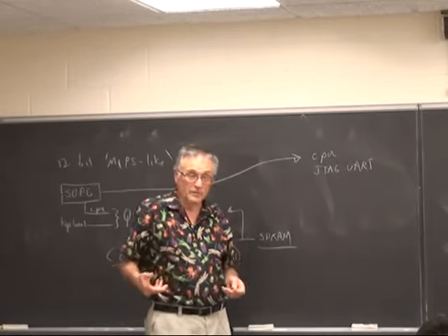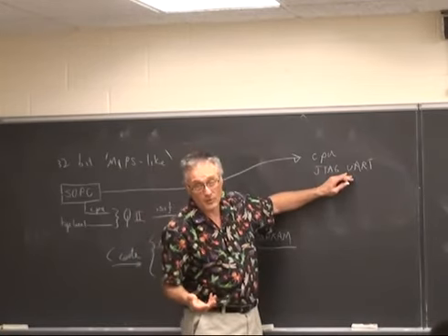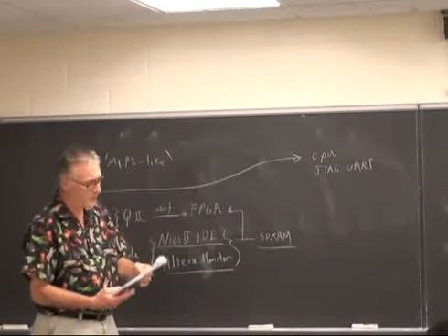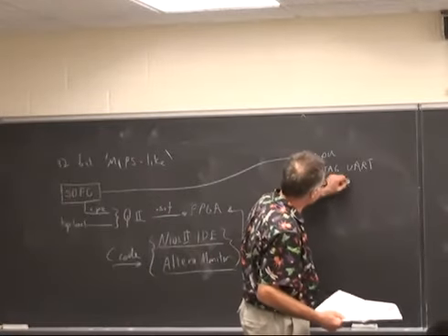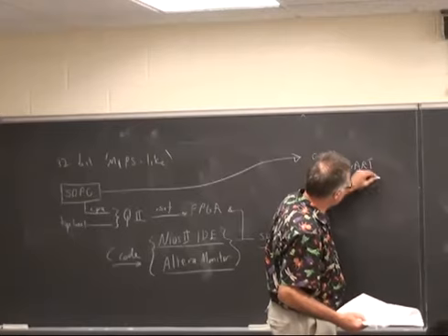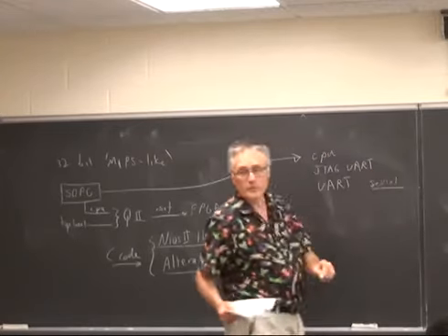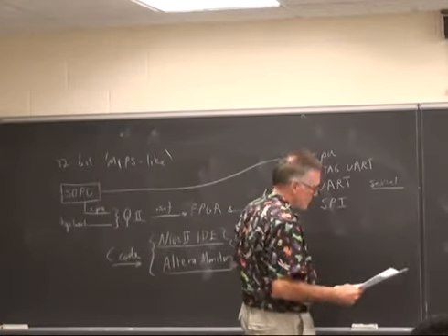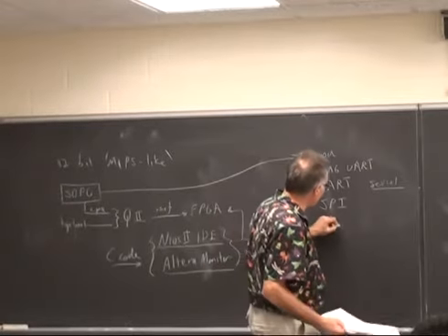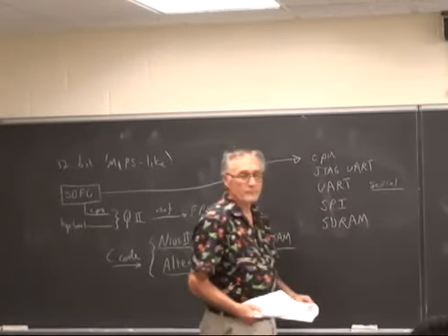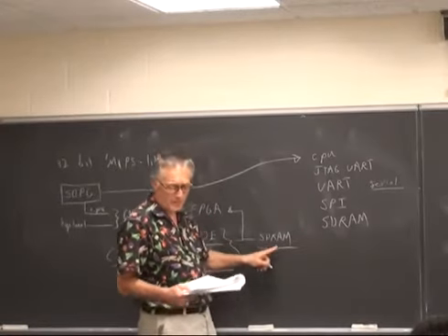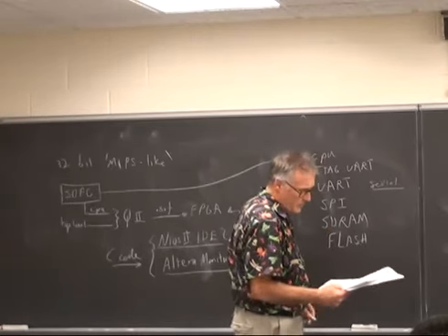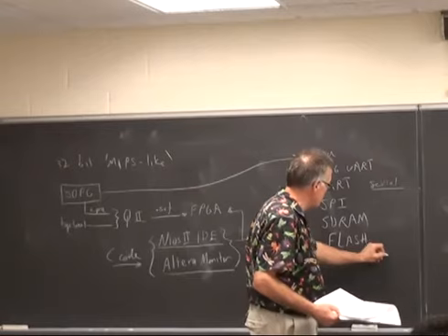And when you do that, you can type into a special console window and use the JTAG UART as an I/O device. There's also a regular UART, which goes through the serial connector on the board. There's a serial peripheral interface device, an SDRAM driver, which obviously you're going to use for SDRAM. There's a flash driver, which I doubt you'll use in this course. An LCD driver, which you will use.